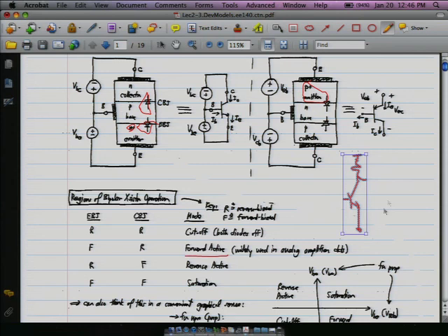All right, so if we have our bipolar up here, let's say that we have a VCC of 3 volts up here, and that this is grounded. Because we want this diode between the base and the emitter to be forward biased, we'll have this voltage be around 0.6 to 0.7 volts, depending on the characteristics of the device.